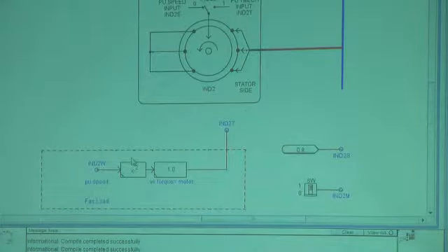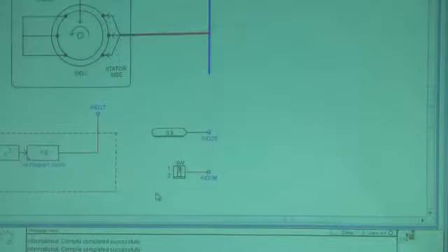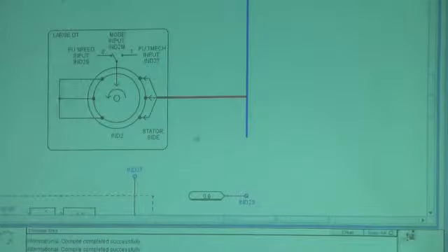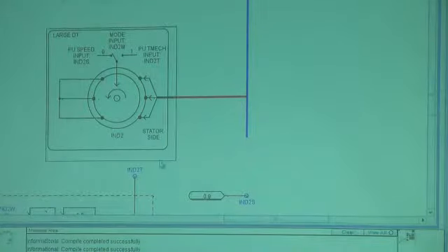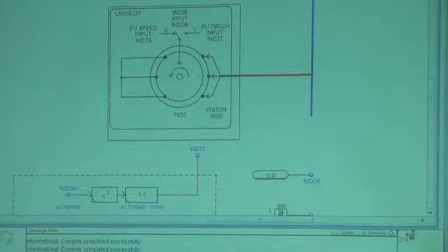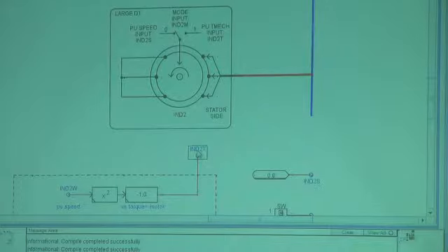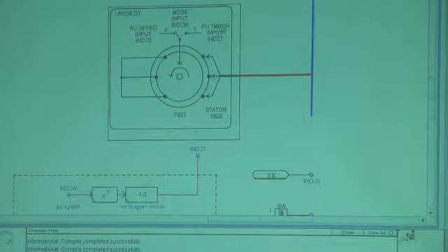This little circuit here just creates typical fan load. So depending on what the mode input is for this motor, you see this IND2T, that would be your mechanical torque input, and then IND2S would be a speed input.